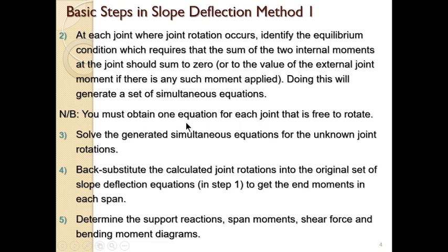Note that you must obtain one equation for each joint that is free to rotate. So any joint that is not fixed, you must derive one equation for them. Now solve the generated simultaneous equations for the unknown joint rotations.